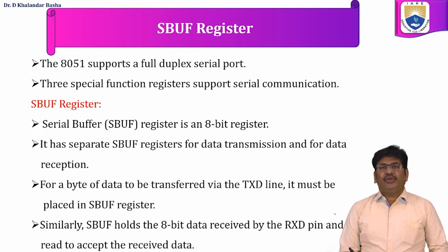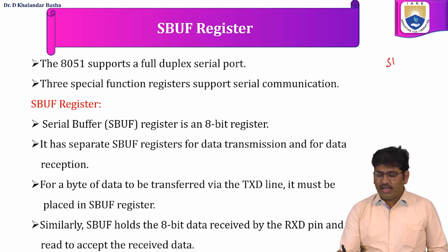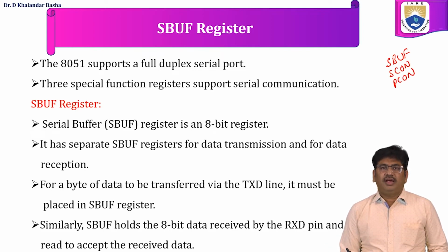In 8051, we have a few SFRs supporting serial communication. The 8051 supports a full duplex serial port, which indicates the data transmission and receiving of data take place at the same instant. 3 special function registers support serial communication. They are SBUF, SCON, and PCON. These are the 3 SFRs used for serial communication.